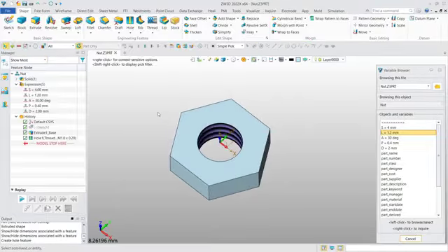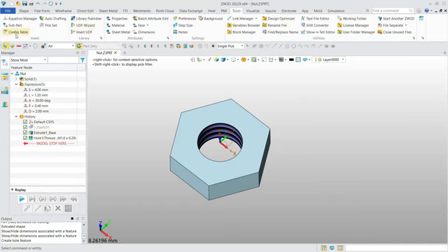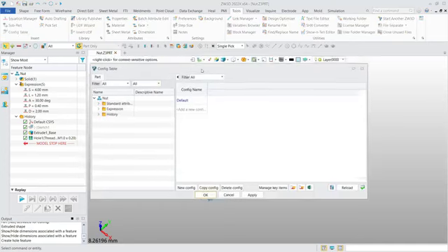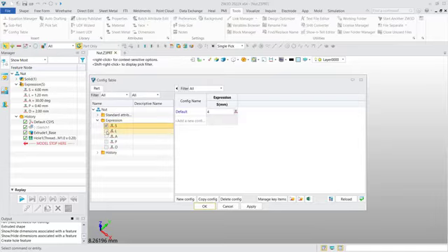This is the result. And maybe there are some more details about the nut, but we will just ignore it to save you more time. And the next step is to create different part configs. Here we use config table. Here we can show all the expressions. Then we can create configs based on them. We can select the configs we want to add.